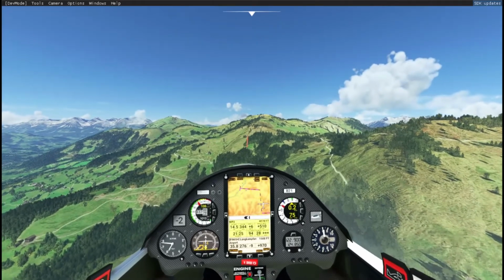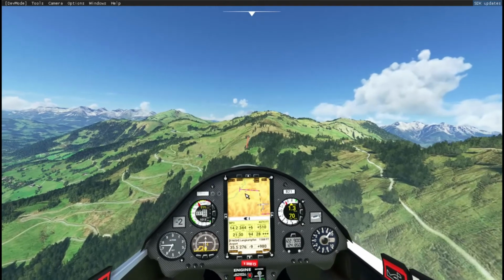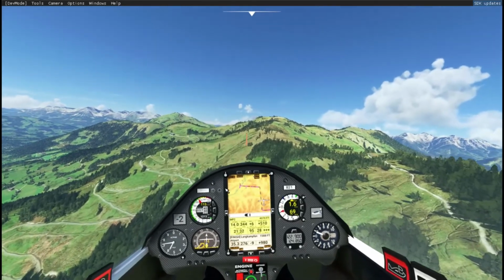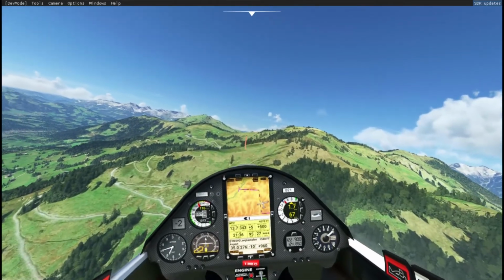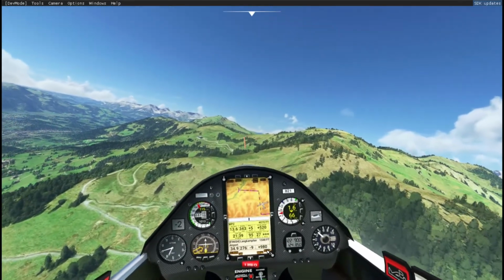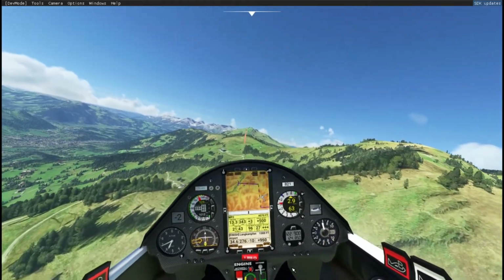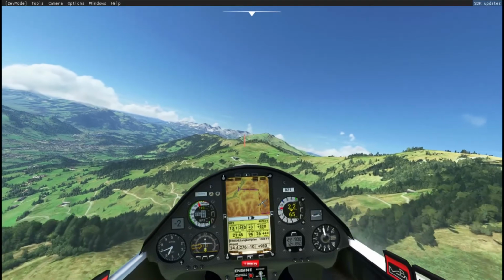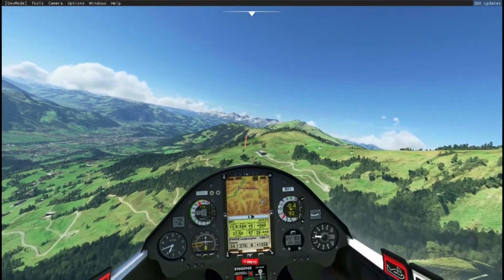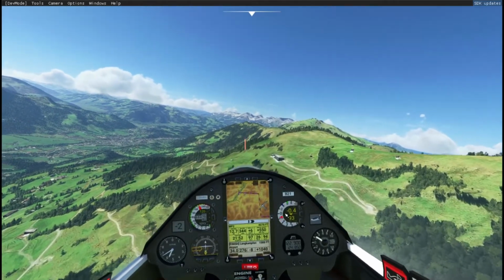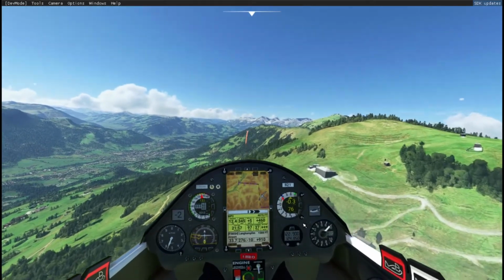We're going to get ridge lift on that east-west route as well. Remember the wind direction. So basically, I'm flying now, keeping the arrival height at the final waypoint round about 1,000 feet. If it goes too low, I'll slow up a little bit. And hope I've calculated 1,000 feet well enough. And this figure here is dependent upon the speed I've told this whole computerized panel I'm going to fly at, which I did via this MacCready knob.